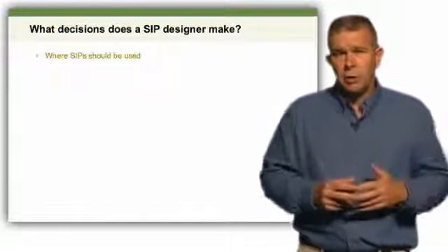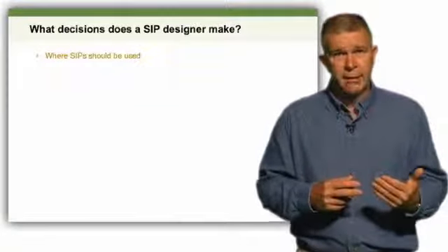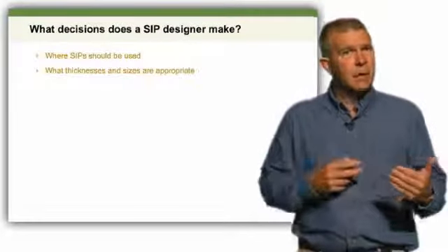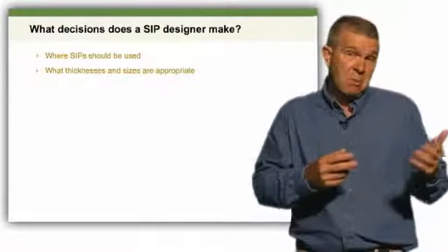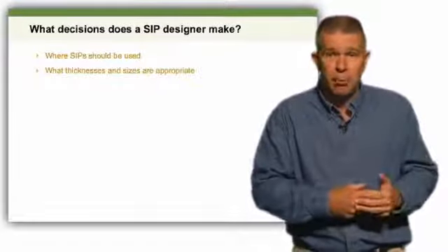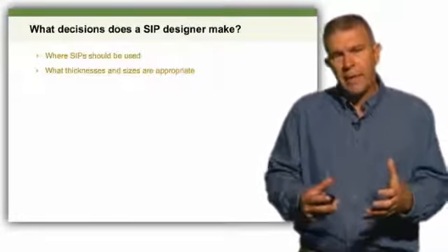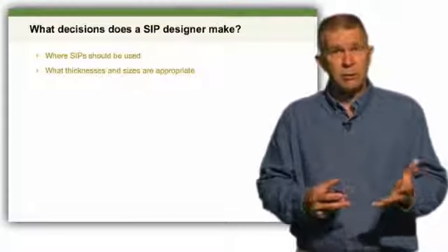Then one of the number one questions that's often asked is, what is the thickness of the panel that we're going to use, or what size panel? And this has a lot to do with the conditions of the job site. Maybe it has to do with the capabilities of the panel provider. But you need to understand, as the SIP designer looks at this package, needs to know what thickness panel are we using and what size panel.